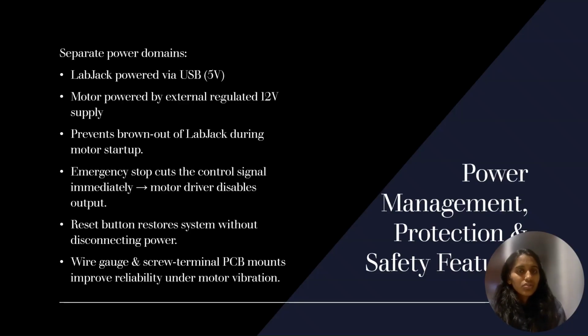We also used screw terminals, thicker wires, and proper grounding to make sure the circuit stays stable even when the motor is vibrating. All these safety features ensure that our system is reliable and protected during long-term use.